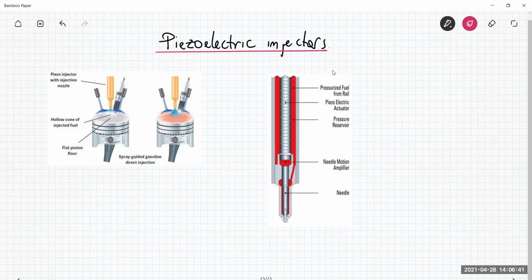Basically, in order to get the best performance from a thermal engine in a vehicle, for example, to reduce the unburned gases generated by the operation of the engine, it is very important to maintain the efficiency of the thermal engine at a very high level. It's crucial to adjust in real time the quantity of fuel that is supplied to the thermal engine.